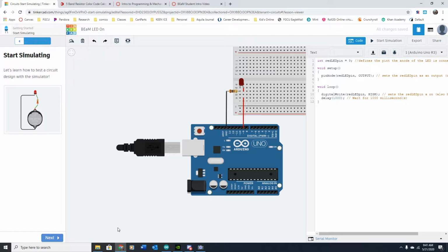So I have this open in Tinkercad, and just to show you this software, I have an Arduino Uno. I've connected the digital pin 9 to a breadboard. Again, keep in mind the pins inside this breadboard, the sockets, attach along each of these rows, and it highlights those inside the system, as well as along these plus and minus columns, although I'm not using those. I've got a red LED, a 100 ohm resistor, and that's going back to ground.